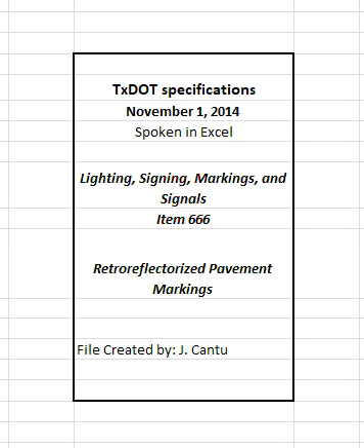4.2 Surface preparation. Prepare surfaces in accordance with this section unless otherwise shown on the plans. 4.2.1 Cleaning for new asphalt surfaces and retracing of all surfaces. Air blast or broom the pavement surface for new asphalt surfaces less than 3 years old, and for retracing of all surfaces to remove loose material, unless otherwise shown on the plans. A sealer for Type 1 markings is not required unless otherwise shown on the plans.